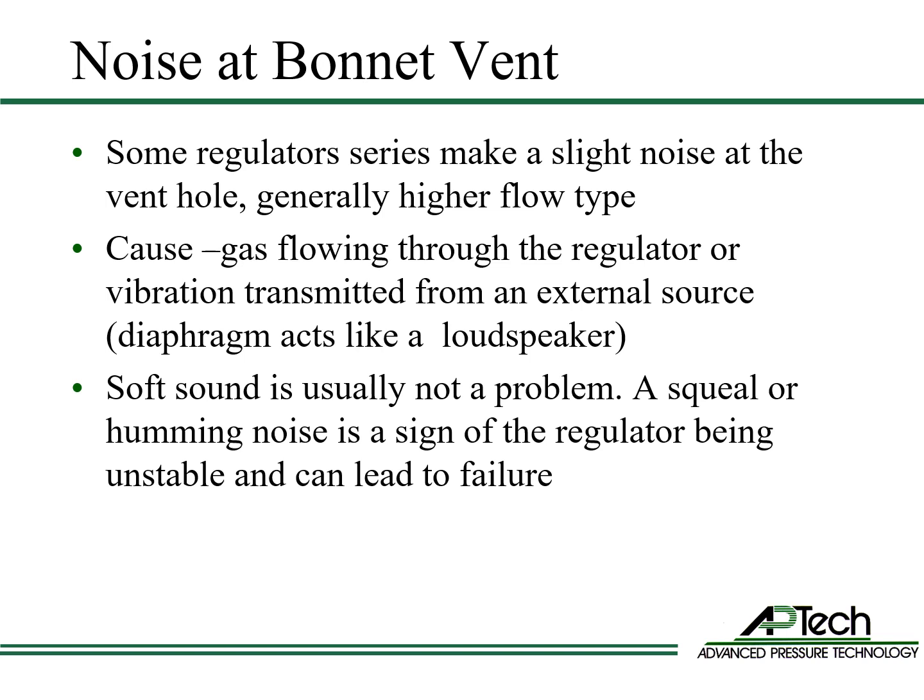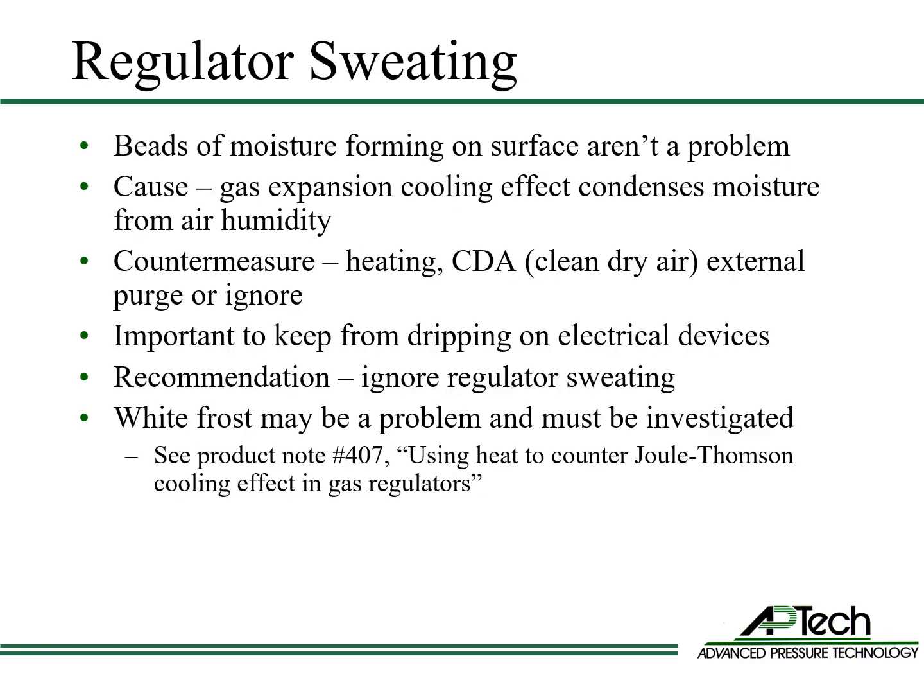A soft sound is usually not a problem. A squeal or humming noise is a sign of the regulator being unstable and can lead to failure. Regulator sweating is when beads of moisture form on the regulator surface and are not a problem.